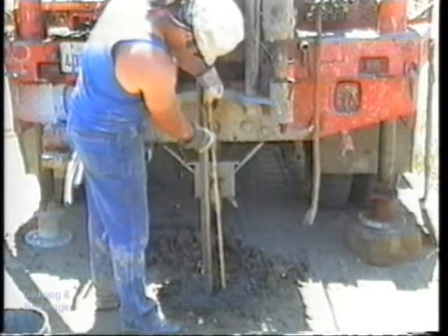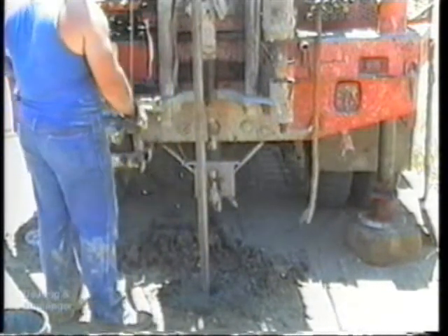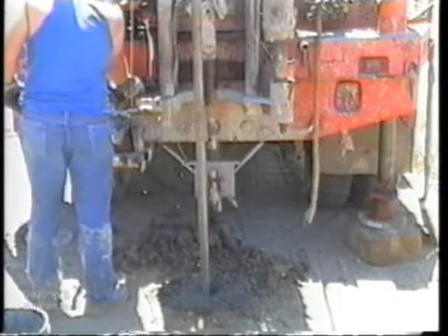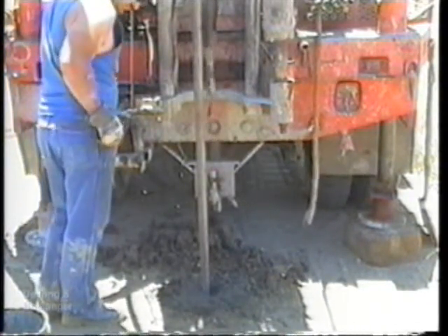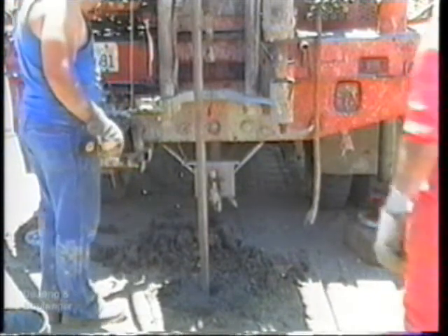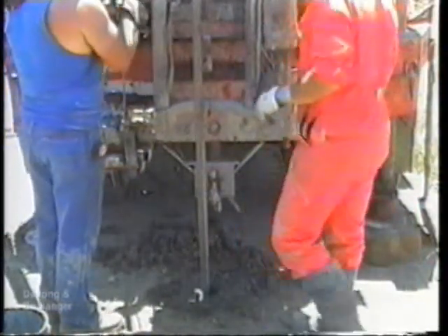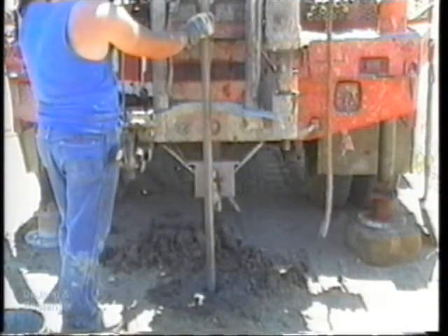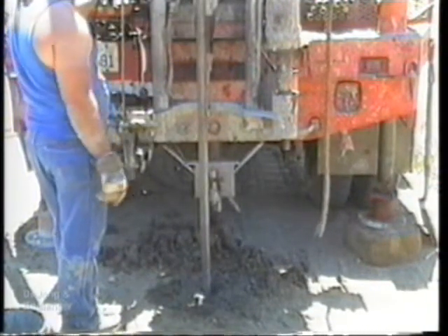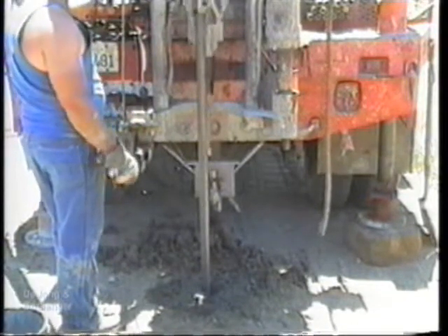The sampler is then pushed downward from the bottom of the hole a distance about 5 inches less than the length of the tube. To minimize the sample disturbance, the sampler is pushed into the ground at a high constant speed. The sampler should not be driven by a hammer, as this increases sample disturbance. After the sampler has been pushed down, the drill rods are rotated to shear the end of the sample, and the sampler is removed.